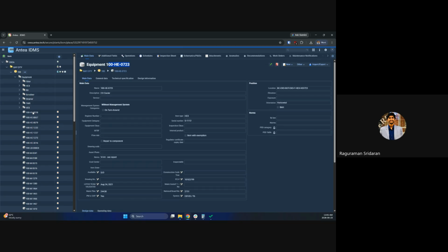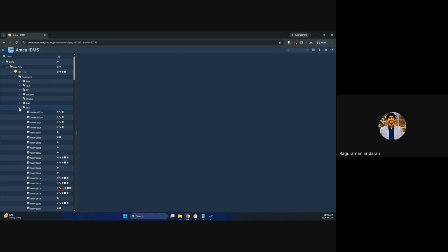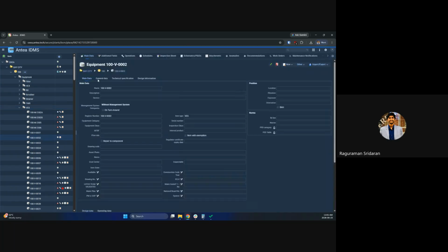But there are some you will find here as well which are not in the categorized state, because these are coming from P&IDs. So if you want to find some asset, for example a vessel, I select some random asset, copy it with the proper process unit, come here and select this magnifying symbol. It's a search toolbar. We paste it. I put the percentage symbol on both sides.